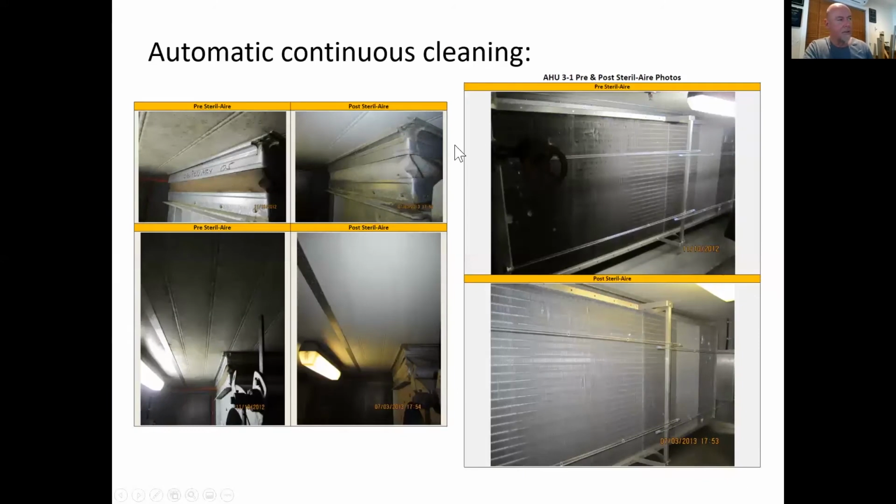There's more examples of cleaning up inside the air conditioning chambers, cleaning up the fans, all the sealants inside the plenums, and that's the coil before and after as well. No manual cleaning done, it's just the UVC.